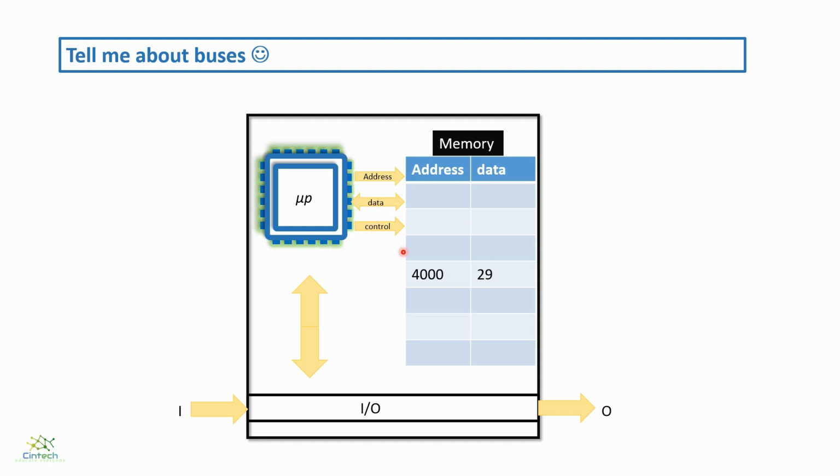Here you can see a simplest representation of a bus. At one end there is a switch that connects the bus to ground. Now say you have to send a 0. Simply close the switch. Now it's connected to the ground. At the other end you get 0. Again when you need 1 at the other end, open it. By TTL logic, floating signifies high. So you see they are this simple.